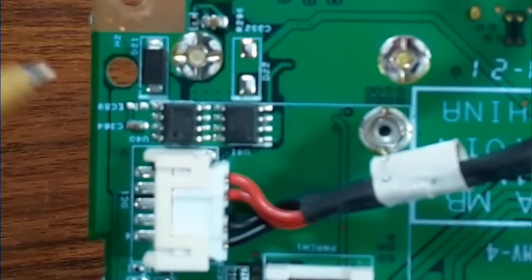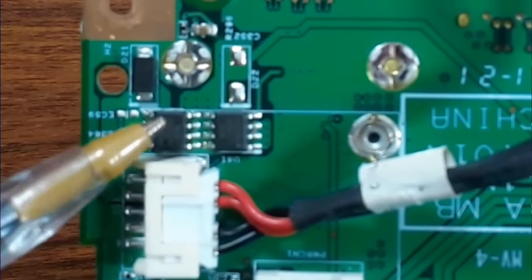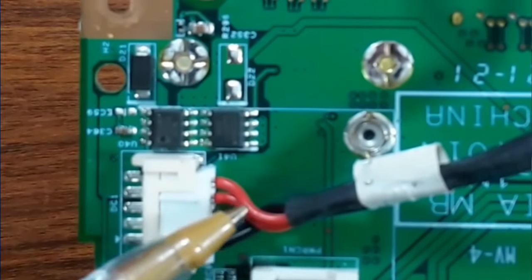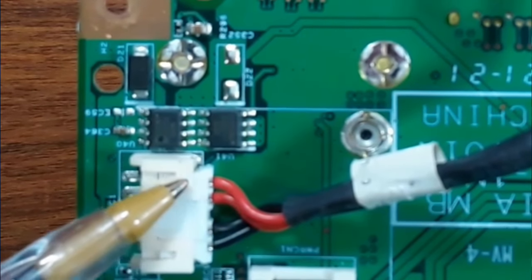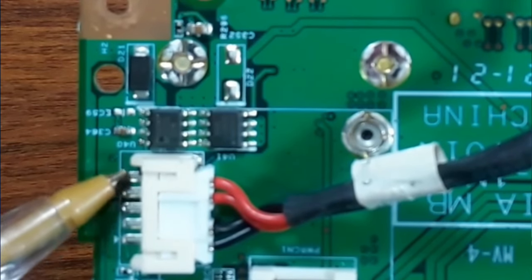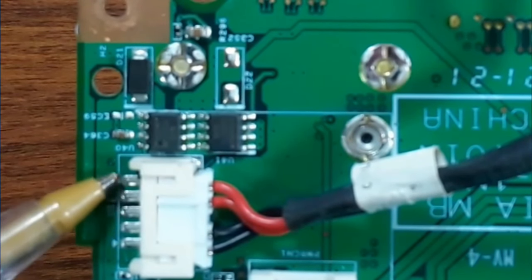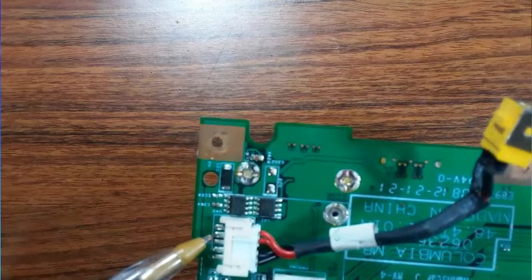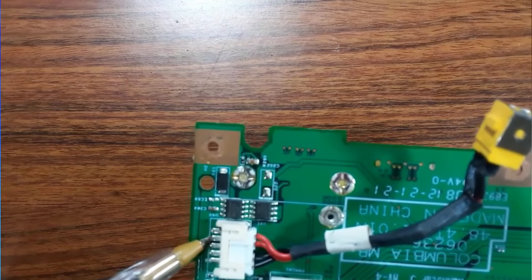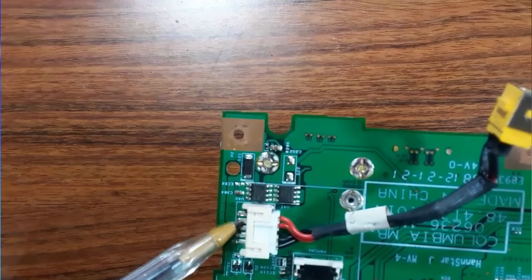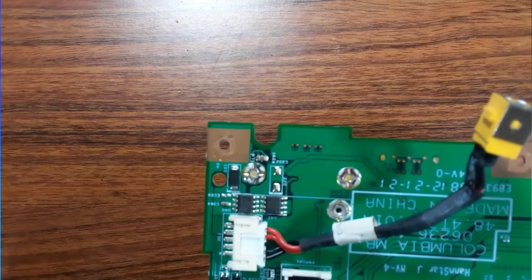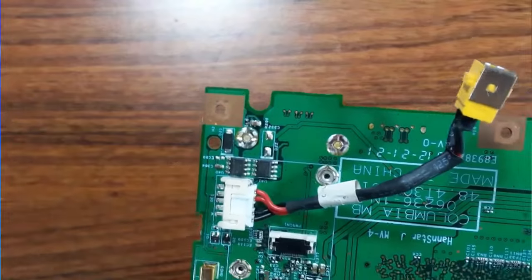Okay, and first, or before checking this component, let's first check the continuity between this red cables, as you see, means the high pins or the positive pins. Check the continuity between this and this. Of course, you will find a continuity between this pins and one of this or two of this. Okay, so let's check it.